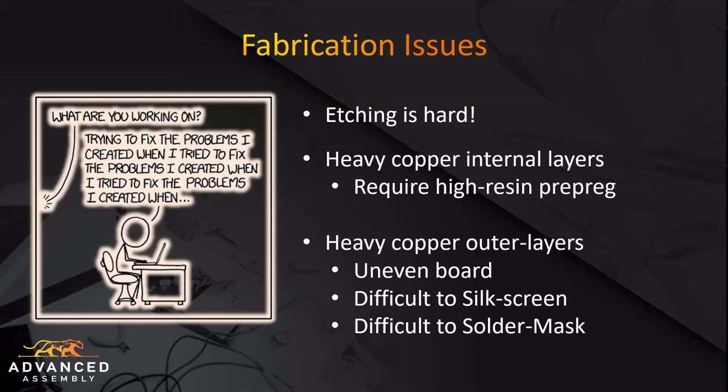Then after the boards are etched and plated, there are going to be other problems. Etched boards require a special high resin prepreg to fill the deep gaps and the voids that are created by etching.